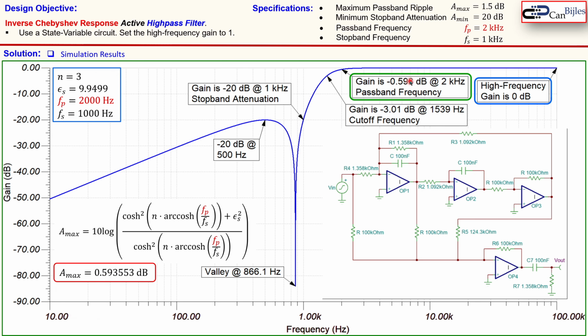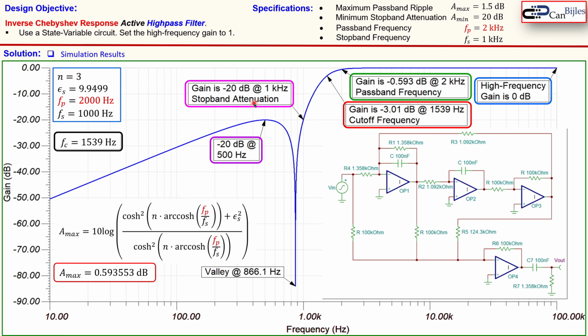And again, we see that at that frequency the attenuation we get is exactly as we have here. But we have here less ripple or less reduction in the gain because we do the frequency scaling according to the stop band frequency. What we also see is that this is going down rapidly and it is increasing. And it comes again to a point which is not above the minus 20 dB. That is interesting, because if I go above, that will mean that I can get a higher gain at a frequency which is smaller. And this happens in this case at 500 hertz.